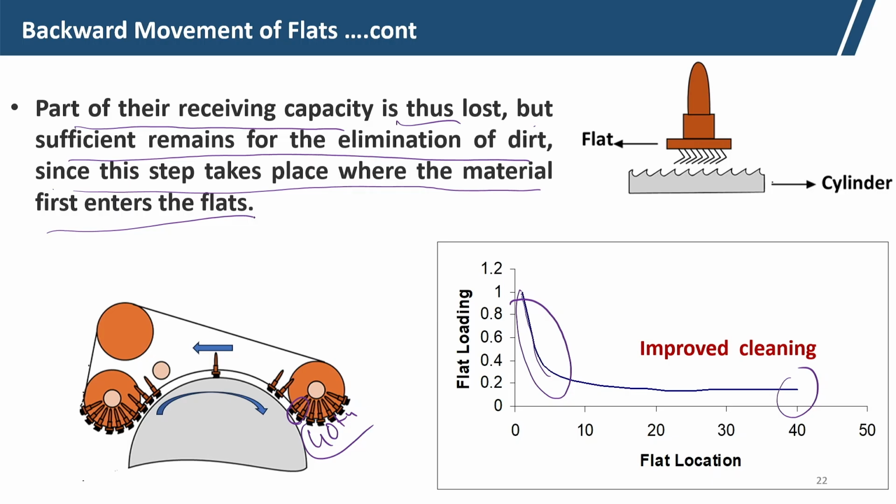Now, that means in this zone, although these flats are loaded with impurities during this entire travel, they still have some capacity, because in the initial portion the fibers are entangled more. So, there the gradual action is acceptable, and it will cover the whole carding zone. So, gradually the flat will be able to open up the fibers.